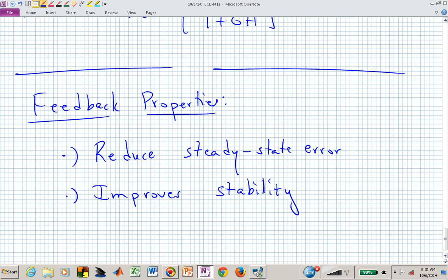In lab number 2, we are actually going to try to change that. We want to use feedback to improve the stability. Now we want to make that angle maybe smaller. Naturally, the system may want to have a huge angle. We want to change it. And we're going to change it not by mechanically changing the system. We are going to measure position and velocity and feed those signals back electrically to change the dynamic behavior of our system. With feedback, we can improve stability.